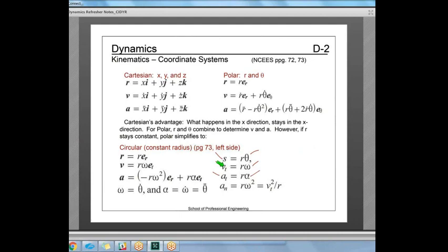If you're trying to write these conversion equations, the thing to remember is S equals R theta, V equals R omega, and A equals R alpha all have in common that there's an R in front of the Greek letter. So at some point in life, you're going to end up in a situation where you're going, I need to get theta turned into an S. Do I multiply by R? Do I divide by R? And you can remember S equals R theta. And the way you keep from getting any of those letters in the wrong place, you just put the R next to the Greek letter and you're good.